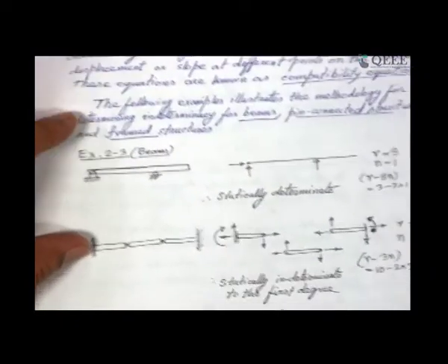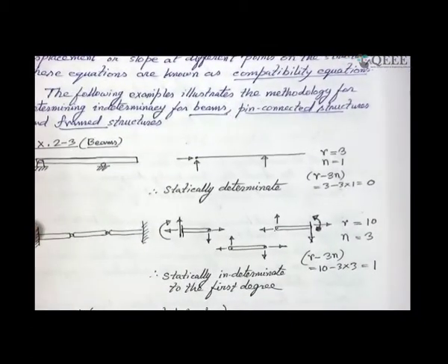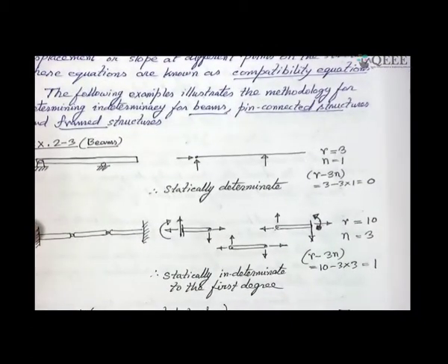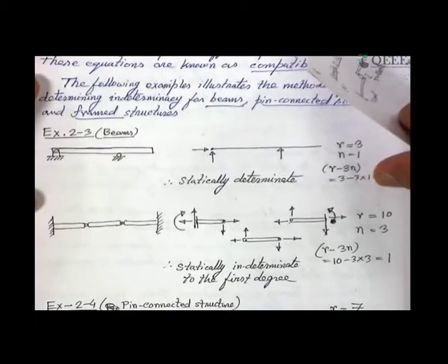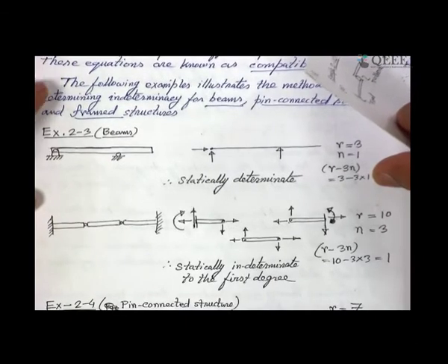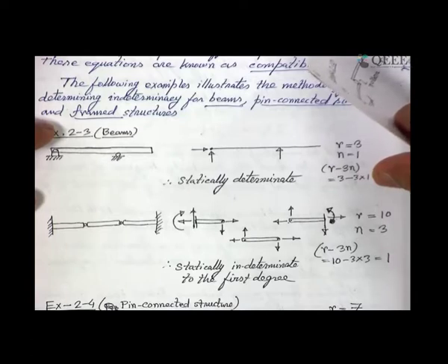You look at it, suppose you are given a beam like this, and you need to find out whether it is statically indeterminate or determinate. This is statically determinate and the calculation shows that, but later on you will find that instead of calculating, you can actually find out by observation whether it looks stable, and whether just the required number of supports are there and no more.